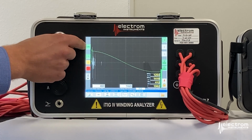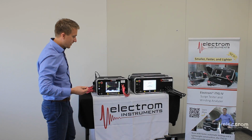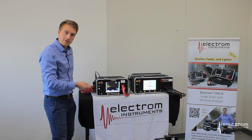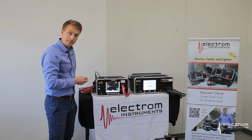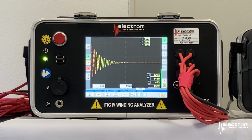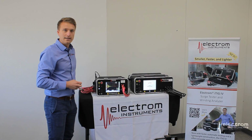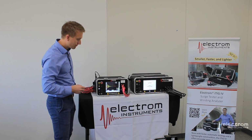Looking at the surge test results, so hiding the PD results, we're now looking at the 3 surge results overlapped. As you can tell, the waveforms are not completely matching, and our percent wave differences are relatively high, and that's because we have a concentric wound stator. In order to make sure that the insulation system in this particular stator is good or bad, meaning do we get the differences in the waveforms because of the concentric wound nature of the stator, or is it because we have poor insulation? To figure that out, we would use the pulse-to-pulse surge test feature. We'll include a link in this video so you can see a demonstration of how that is done.